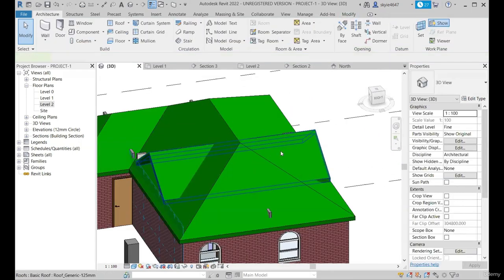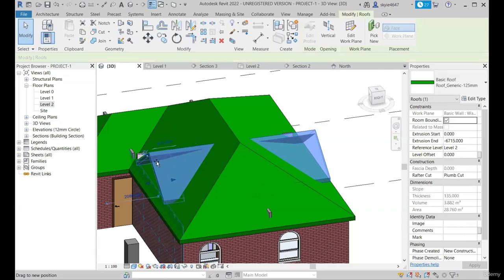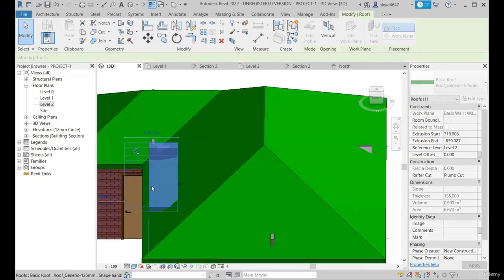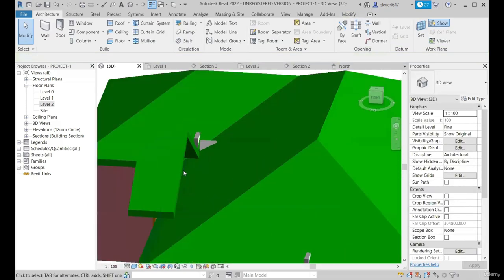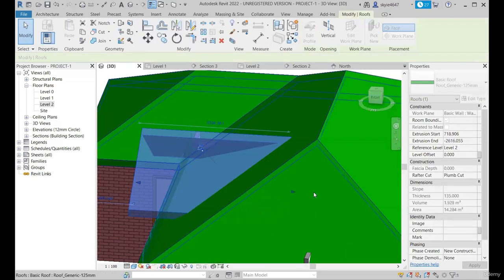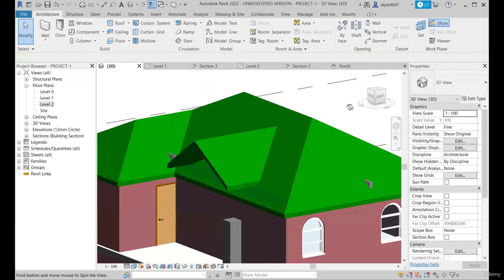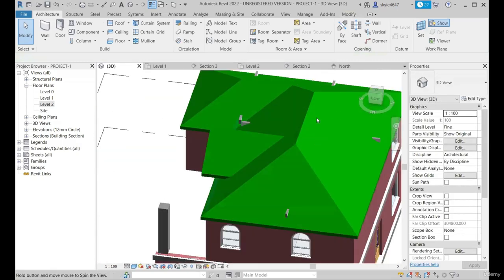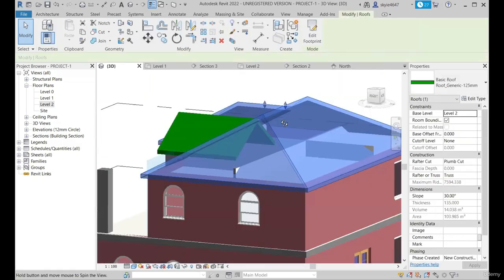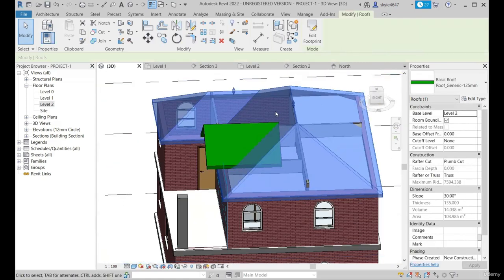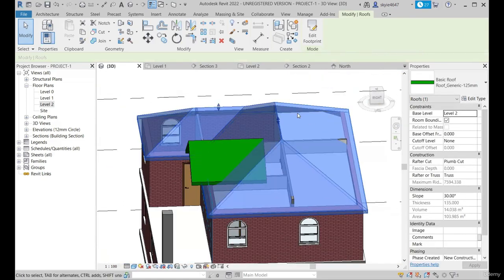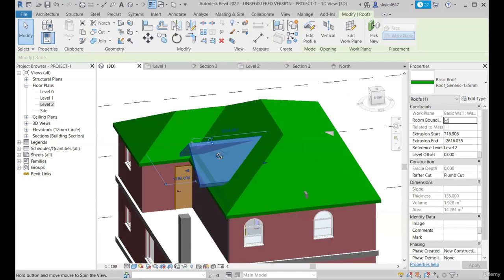You can see this roof is extended here and this is extended here. Now, whenever I drag this roof, it's going beyond the existing roof and is hidden beyond it, but there is no geometry cut. For the smaller roof that we have created, let's make a naming convention: this will be the primary roof and the second one is my secondary roof.